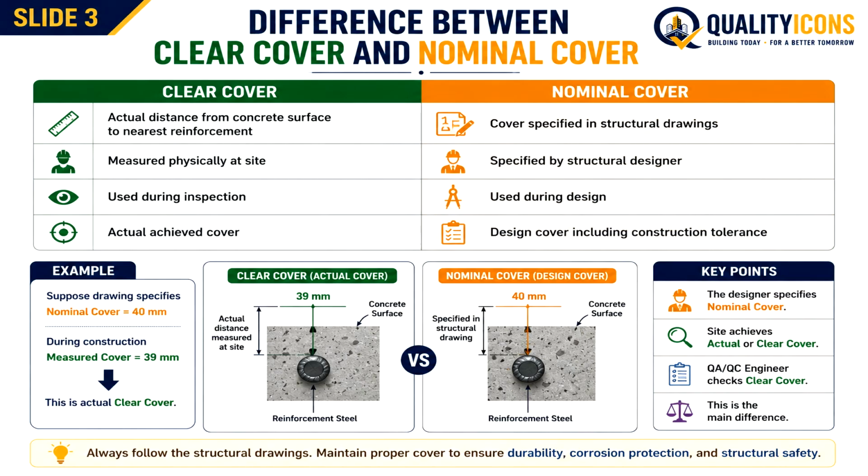Remember this simple formula. Designer decides nominal cover. Construction team achieves the clear cover. Understood? A QA/QC engineer verifies the clear cover before concrete pouring. Never assume the cover is correct just because cover blocks are placed. Always measure.